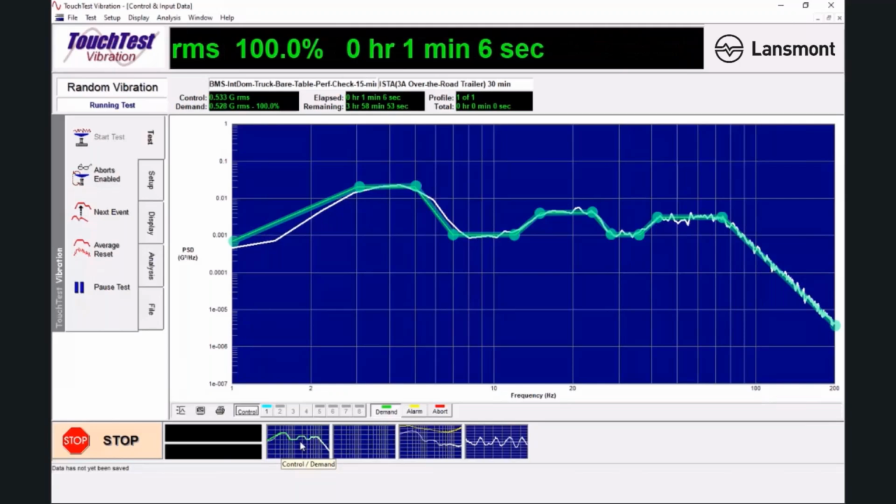So what a vibration controller does is it says, okay, when I do this testing, let's just pick this point. This is 1 hertz, 2 hertz, 3 hertz. It says I'm continuously, when I'm running a test, going to send out a signal over to the vibration machine that has 3 hertz content to it. And on average, the amplitude of that 3 hertz content is going to be this. In the y-axis, let's just say it's 0.02 G squared per hertz.